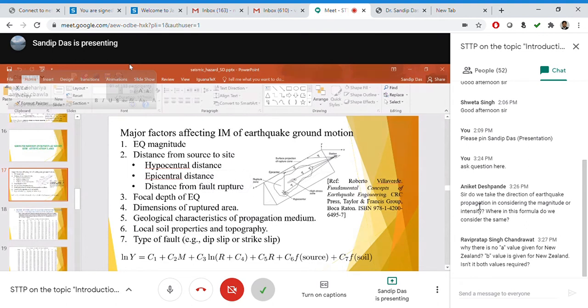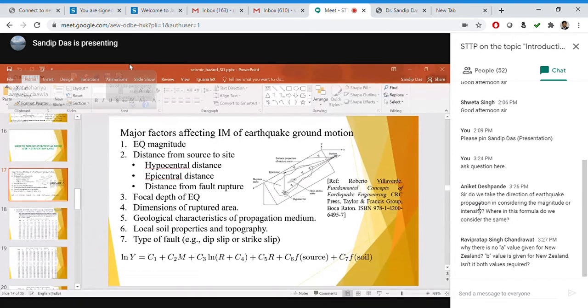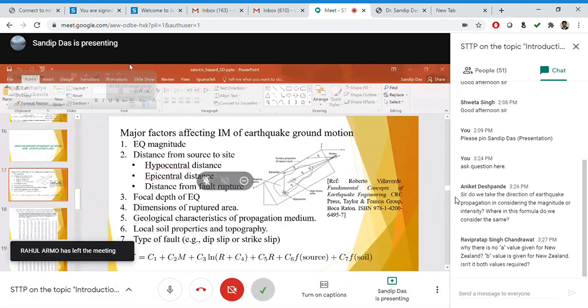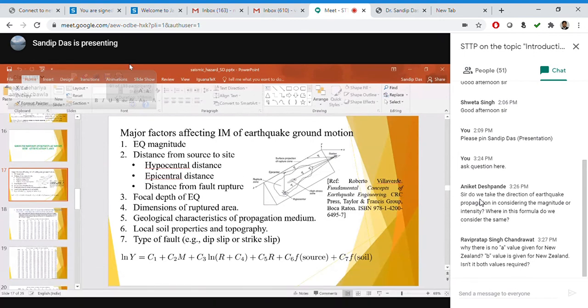But for all practical purposes, especially when we are a little far away, more than 30 or 40 kilometers from the fault, it doesn't really make a very big difference, because the sigma of that attenuation model we're talking about is so large that it will basically normalize everything in some sense. So when you are going for a really stringent hazard level, let's say an exceedance probability of only 1% or 2%, this kind of thing is not going to matter much.